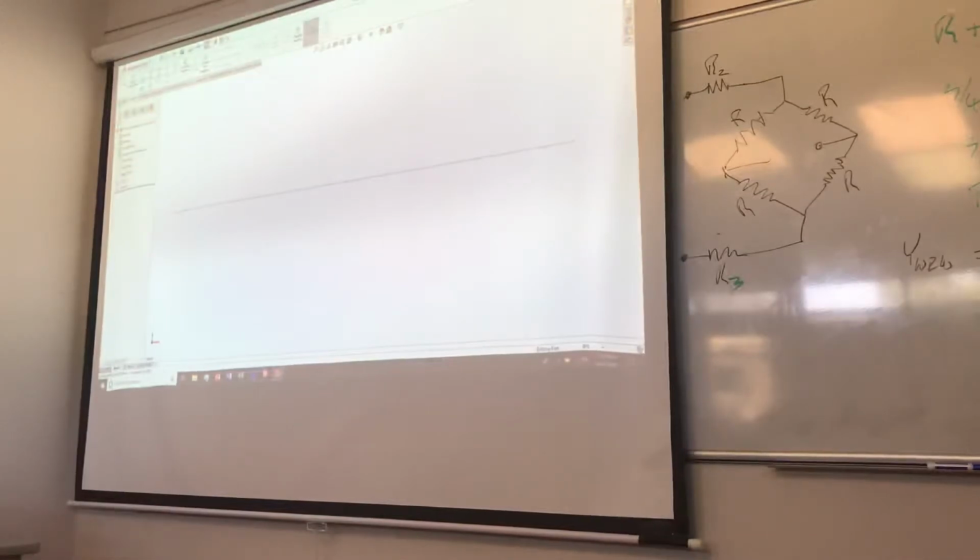So now when I want to make this a profile, I can select on this. I can go insert weldment. Let's try it again. Insert weldments, structural member. Now I should be able to go to custom, pick on my rectangles, and down here I should have my 3 by 1 1/8 rectangle that I made. I pick a group, but I'm going to pick that guy and that guy there.